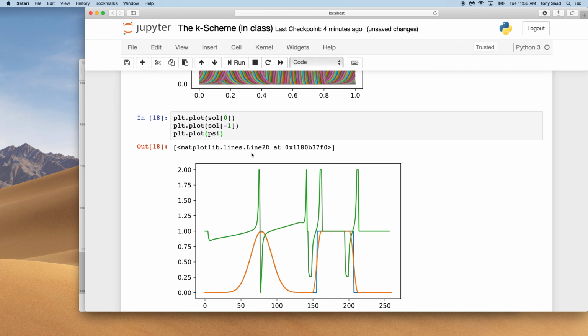You see here psi is nearly going to 0, closer to upwind, and with this gradient it's going up to 2 in these regions, so it's going to pick the downwind case. Now remember, psi is a function of r. It's shifted to the faces, so you have to shift this by about half a point. And here in this non-monotonic region, we're going to go between 2 and 0. So we're going to upwind and downwind accordingly, and that's why you see this thing flatten out.